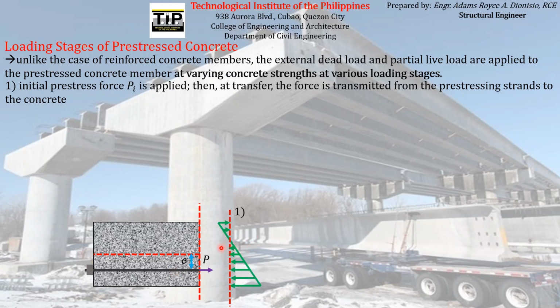This is the result of the stresses coming from the prestressing force P sub I. The total stresses you are seeing here are the effect of the axial compressive stress plus the flexural stresses induced due to the eccentricity of the prestressing force.